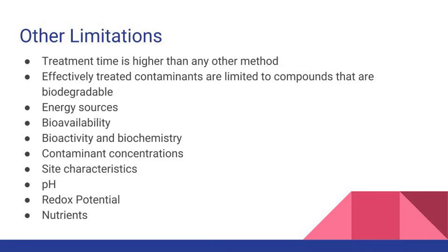In addition to this, we also have another factor dealing with contaminant bioavailability. This is different from bioactivity. Bioavailability depends on the degree to which the contaminants absorb to solids or are trapped by the molecules in the contaminant media, or are diffused in macropores of the soil and the sediment. Other factors include whether the contaminants are present in a non-aqueous phase, such as DNAPL or NAPL.